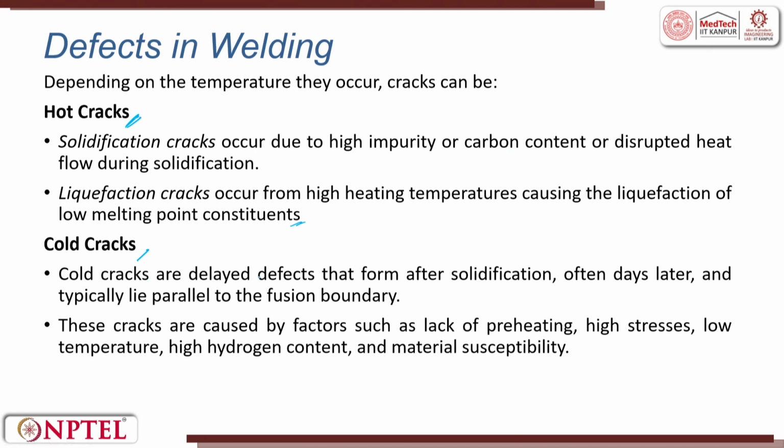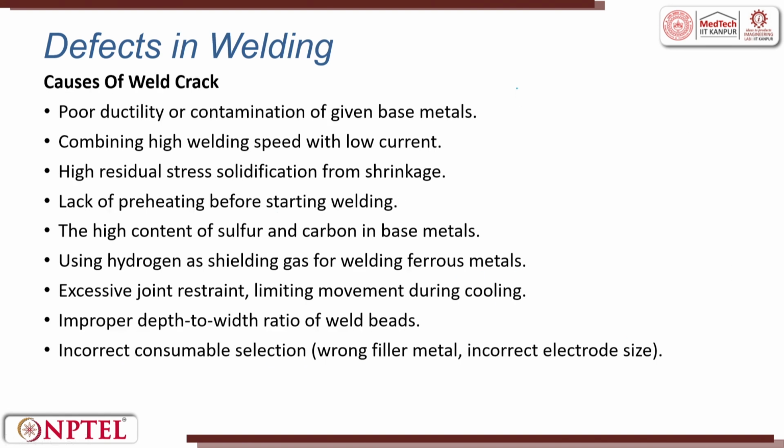Cold cracks are delayed defects that form after solidification. During solidification it is hot; after solidification it is cold. These cracks are caused by factors like lack of preheating, high stress, low temperature, high carbon content and material susceptibility. So these are all the possibilities for defects to happen.